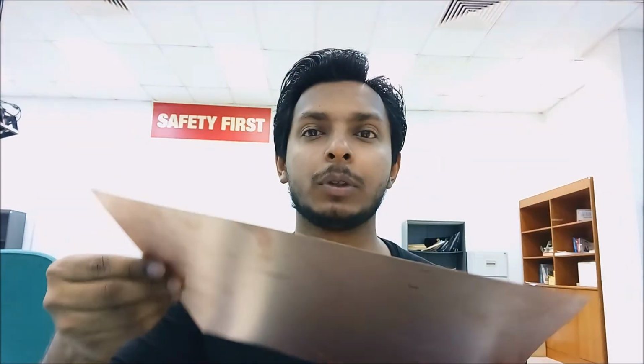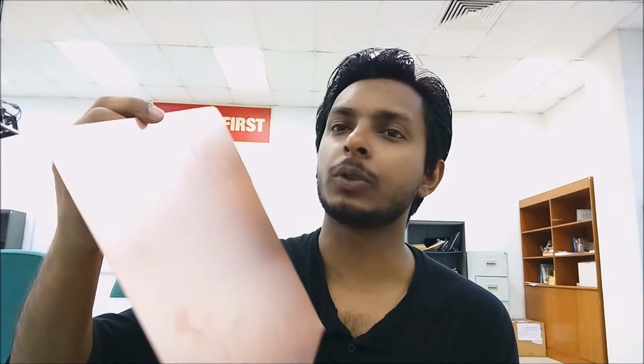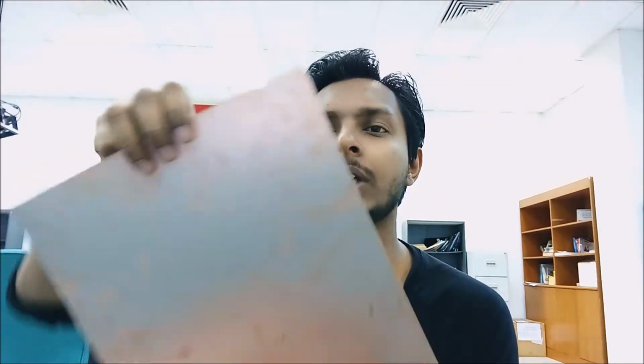Having said that about the properties of our substrate in the design process, while discussing the export and import step, we already mentioned the Taconic TLX8 substrate, and this is a sample of the Taconic TLX8 substrate. You can see this is the surface of the copper plated area. It's an identical surface, so both sides are identical.